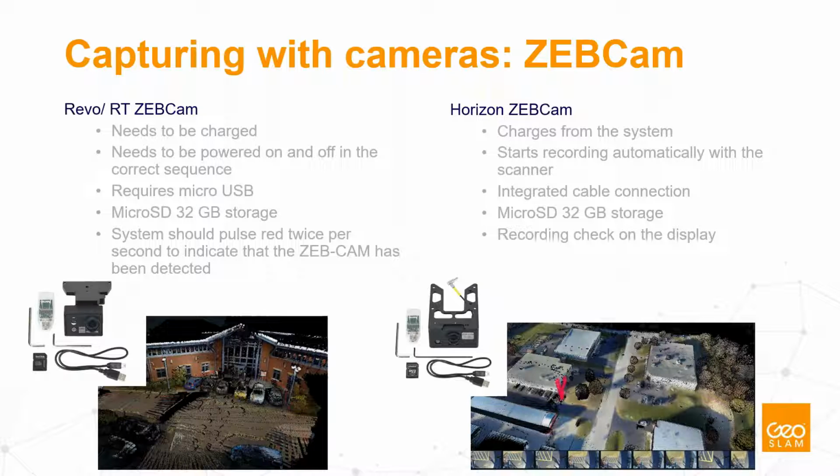Vertically, it's much less than that. So if you're capturing buildings, you might want to paint the building up and down to make sure that the entire structure is in the field of view of the camera as well, not just at the edges, because the edges are distorted with such a wide field of view. Those distorted parts are not used for colorization.